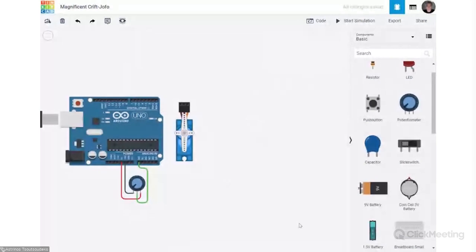Before I connect the servo motor, I want to make some code and read the values from my device. This is supposed to have a voltage of 5 volts between terminal 1 and terminal 2. And by connecting the wiper to any of the analog pins, I can take anything from 0 to 5.